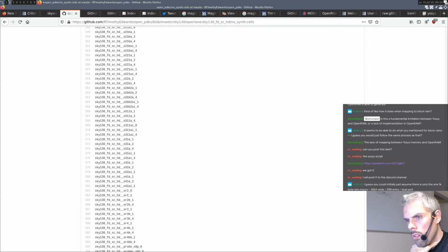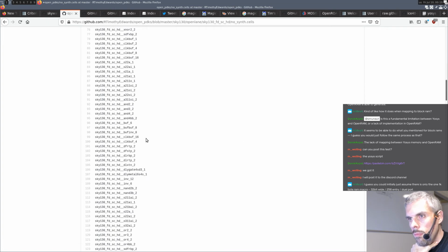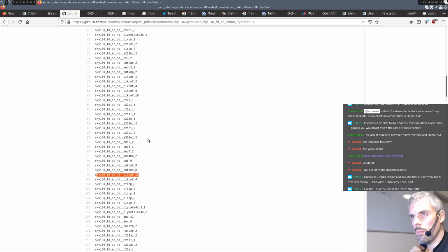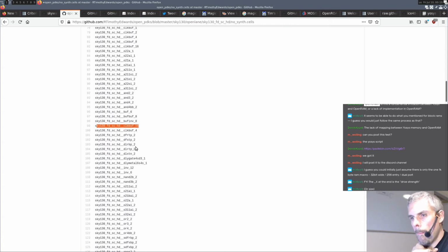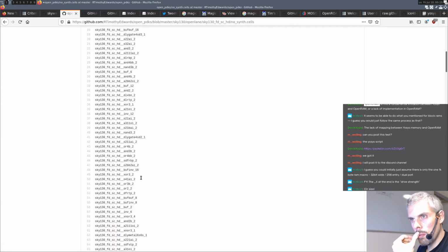I mean, things like clock buffer, that's something you don't want to infer manually, because that just looks like an inverter, or a buffer. But like an OR2 gate, why shouldn't it use that? That's what I'm not sure about.